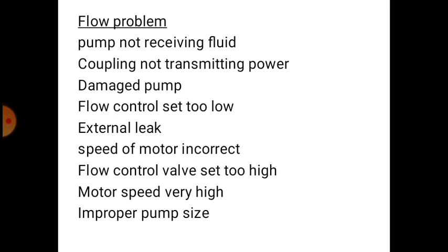So the problems of high flow, no flow or low flow: pump not receiving the liquid or oil may be due to the coupling not transmitting power, or a damaged pump. It may be due to flow control set too low, or external leakages. If the speed of the motor is incorrect, that's why a flow problem will occur.